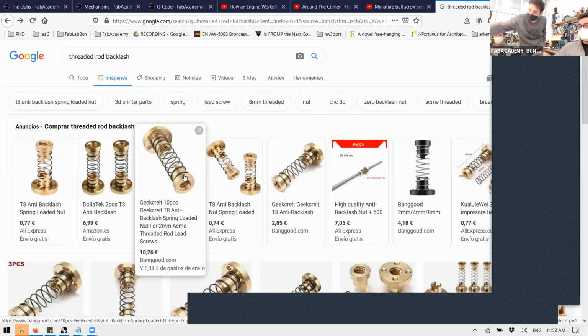Actually, here in this guy, and also here, we have a nut, here we have another one, and inside this one we have a spring to push it. So it's a backlash reducer. It's a good solution, but it's cheap. We cannot go to microns accuracy with this machine just because of that, and because this is not perfectly machined to microns accuracy.